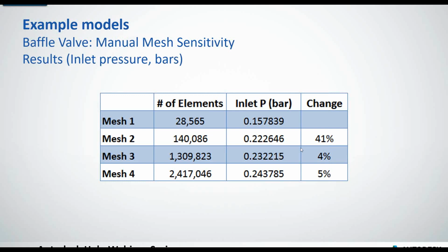So really, I got the most bang for my buck with mesh 2. If I didn't do the other three, the improvement is maybe all I need right here. After that, it's incremental. Of course, on such a small model, it doesn't really hurt you to do that, but on a big model, it might take way longer to go to almost 10 times the number of elements. So that could cost you a lot in time, and it's not going to give you too much advantage.